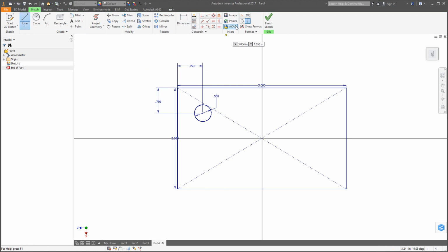I'm going to go to the line tool and transform the line tool to a center line. Center lines are necessary in order to use for mirroring. So I'm going to lock into this vertical line here and click and just connect it to the origin. Click and drag out a horizontal line. Click and then hit escape to get out of the tool. Now, the vertical center line is going to mirror this circle over to the right. The horizontal will mirror it below. You can only do one at a time, unfortunately, so you can't do everything in one shot. So here's what we're going to do.